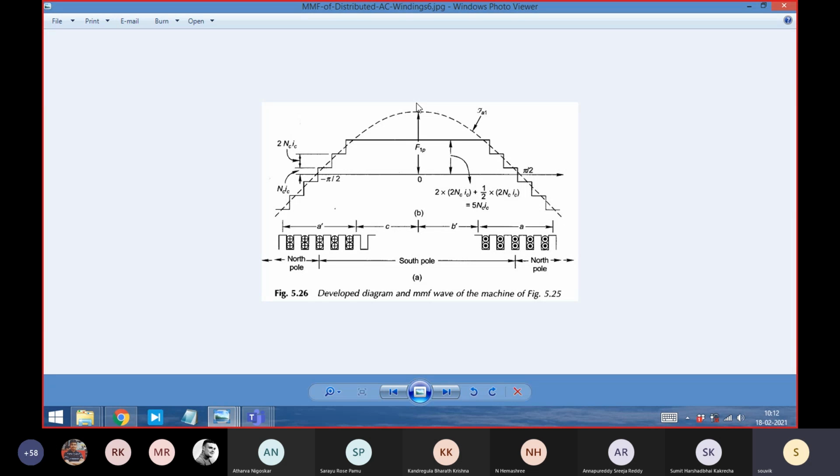Now similarly for the B phase and for the C phase, whose coil axes are 120 degrees shifted. Okay, and individually you are passing current into coil A as well as coil B and coil C. And as you know, these currents are not synchronized in time phase. The currents have a shift in time. So this time shift in the coils means that in the A coil it may be cos omega t, in the B coil it can be cos omega t minus 120 degrees, and in the C coil it may be cos omega t plus 120 degrees.